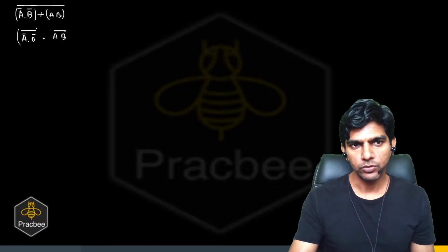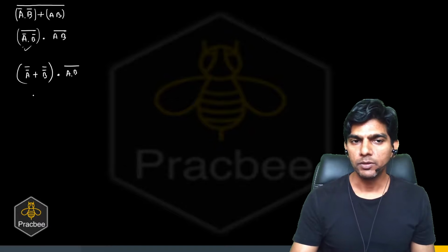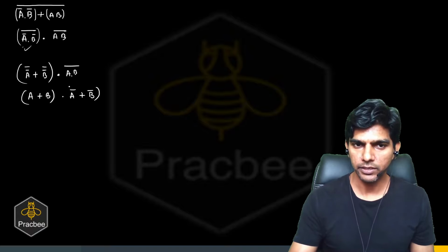Now let us apply De Morgan's theorem for this multiplication. So this can be written as (A double bar plus B double bar) multiplied with (AB) whole bar, right? A double bar is A, B double bar is B, multiplied with (A dot B) whole bar. This can be written as A bar plus B bar, De Morgan's theorem.